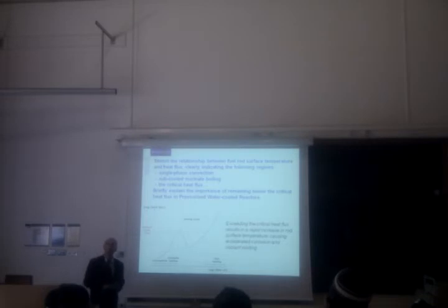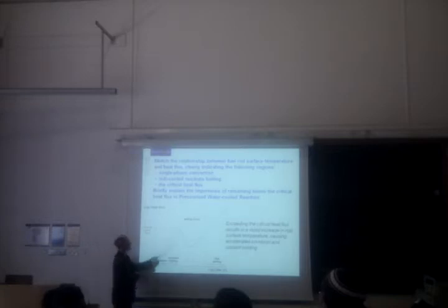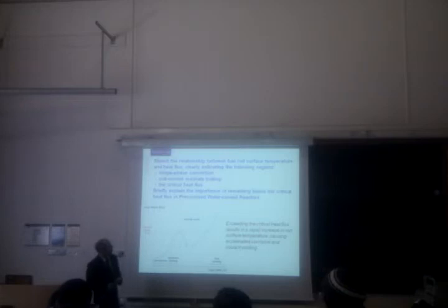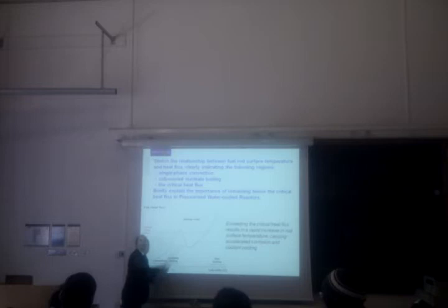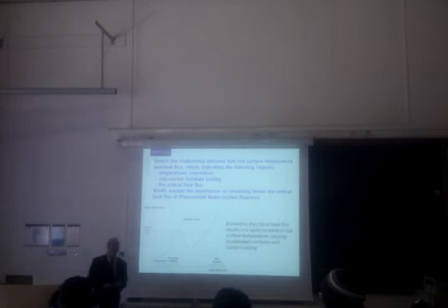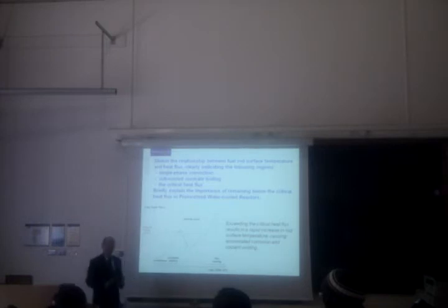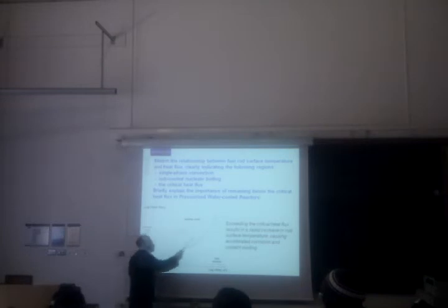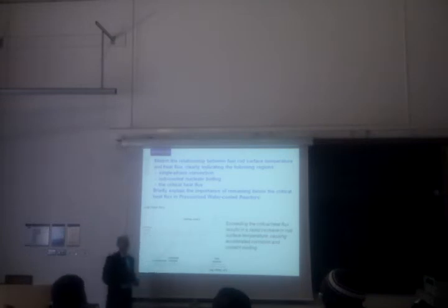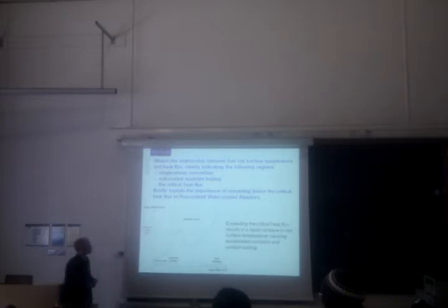In the dip, is it the bubble is insulating it, then as you put more energy in, that sort of allows the... Yeah, it does. The dip is, every year I say the same thing, and every year I forget to do it. I should show this dip region actually as a dotted line, because experimentally you can persuade the fluid to undergo that region, but in reality what happens most of the time is that you actually jump across from operating here straight across to operating here. This region is highly unstable and very difficult actually to reproduce experimentally.